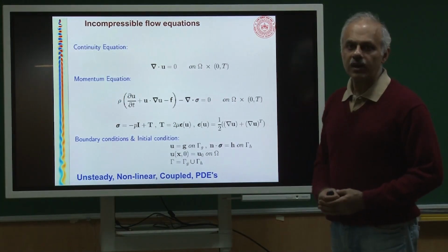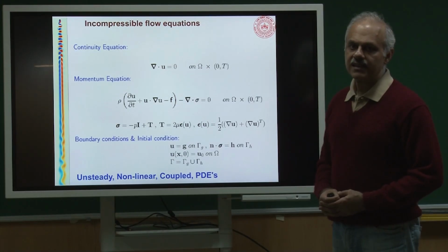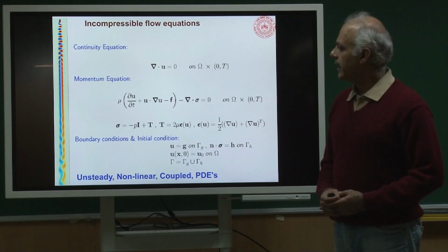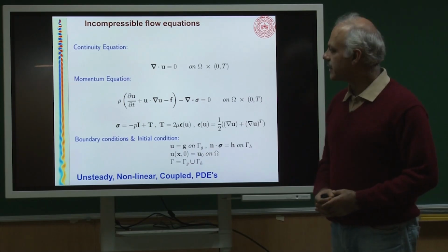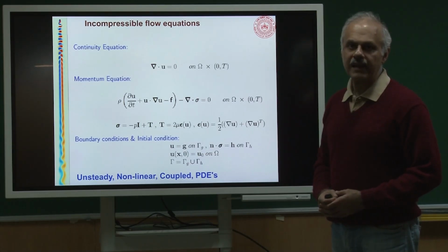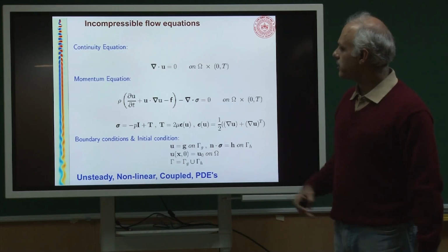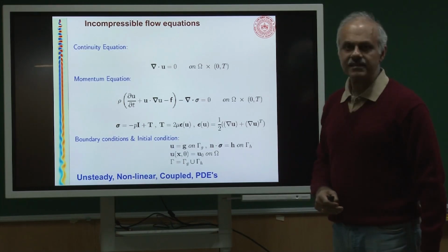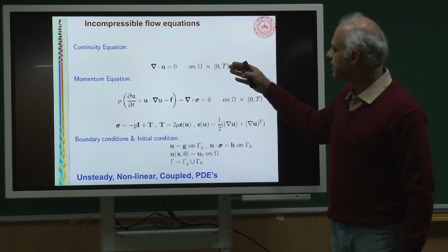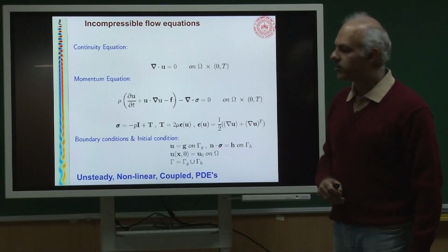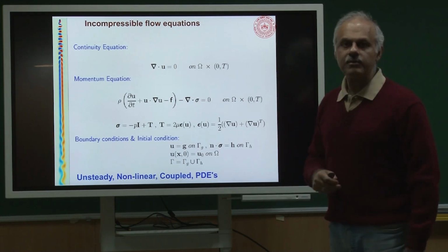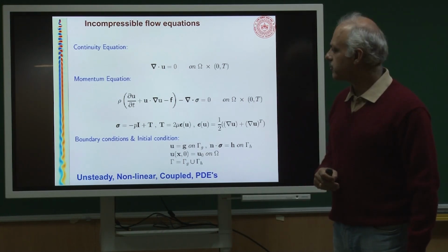So, how is all this modeled? So, the backbone of all this is a model. Okay. And in this picture I have shown you the incompressible flow equations. So, one can assume that let the flow be modeled by certain balance laws, and what we have shown here is the mass balance, which is simply the divergence free condition on the velocity field, because it is an incompressible flow. The equations would look a little bit more complex if it is a compressible flow.